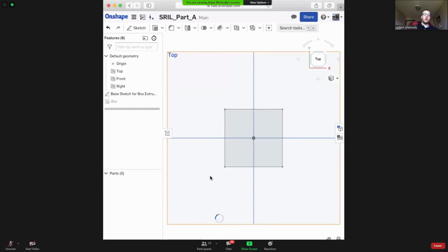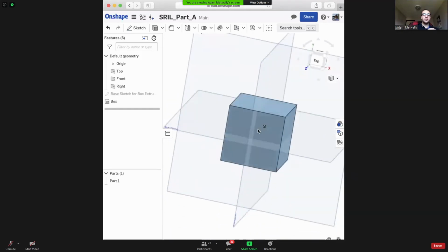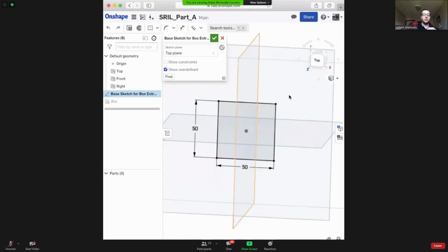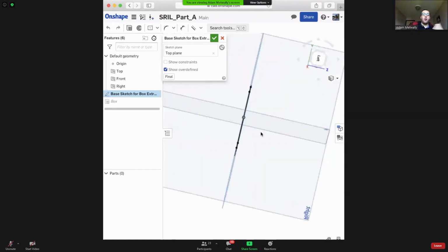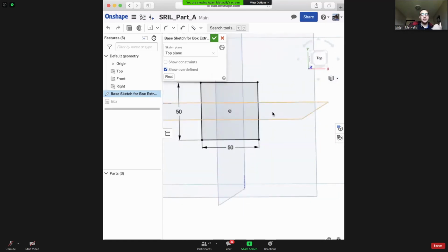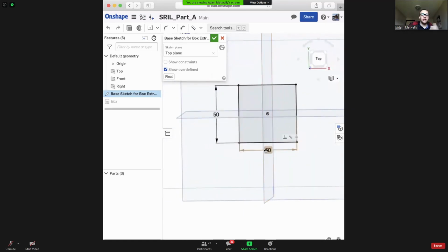So that's another thing to notice, is that say I know for sure that this is going to be a rectangle or a cube or a square, this would have been the better way to do it. Why? It's faster, it's easier, and say I want to change the length, if you guys remember, I had to change 4 dimensions last time when I drew it with the lines. This time I just have to change these 2 dimensions.